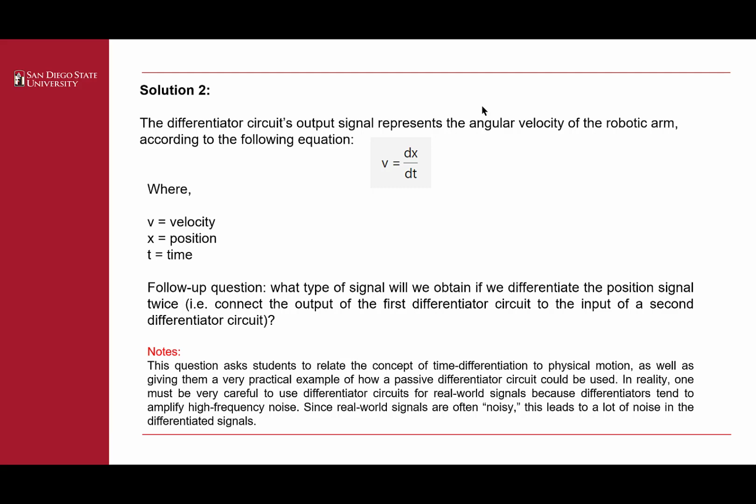Since real-world signals are often noisy, this leads to a lot of noise in the differentiated signals. But if we have to use a differentiator, this is not the end of the world. We have many filter circuits, filter designs that can work pretty well with avoiding these noises or eliminating these noises if they are already added to the input signal.